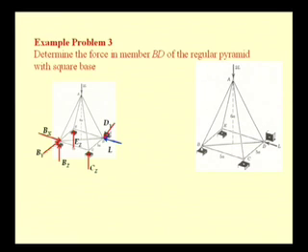But let us see this problem. Here we are just interested to find the force in the member BD. In order to determine the force in this member BD, we can either consider the equilibrium of this joint or the equilibrium of this joint, and the only criterion that has to be satisfied is that since in 3D from the force summation equations we can determine 3 unknowns, at a joint we should only have 3 unknown components of force to be determined.